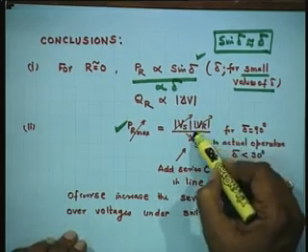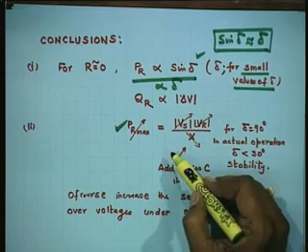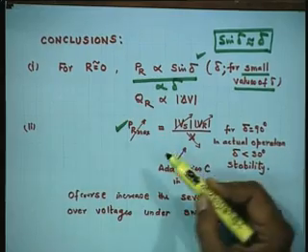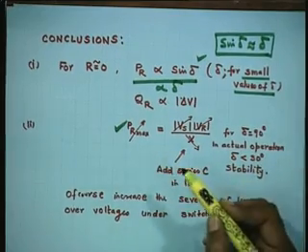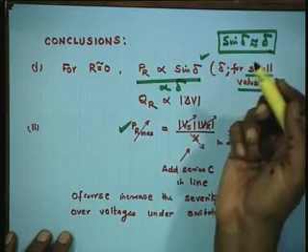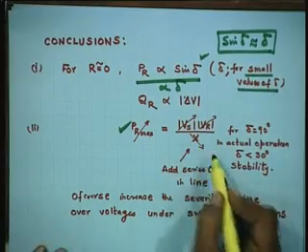Increase Vs and Vr as much as you can, but there are physical limitations. You can't make it 1 lakh volts or 1 crore volts. So, there is a limit of 800 kV, 765 kV or whatever, in the world 1300 kV. After exhausting that avenue, the next is to reduce X.